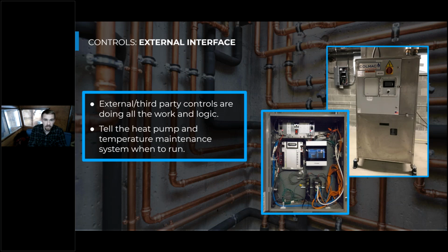So there's a big advantage here in that the external controller can satisfy as complicated of a sequence of operation as it needs to, but the disadvantage is whoever's designing those controls really needs to know what makes that heat pump tick and how this heat pump operates most efficiently within the rest of the system.